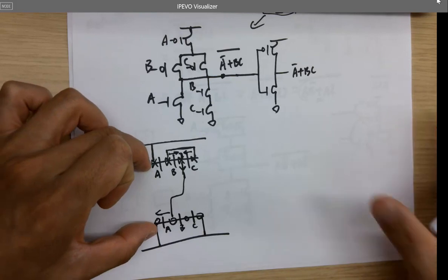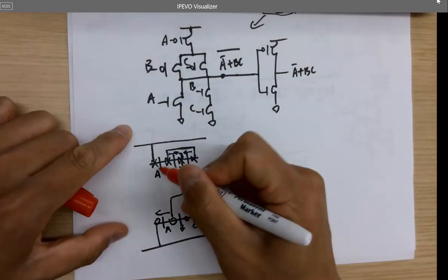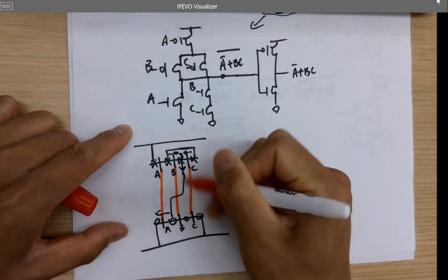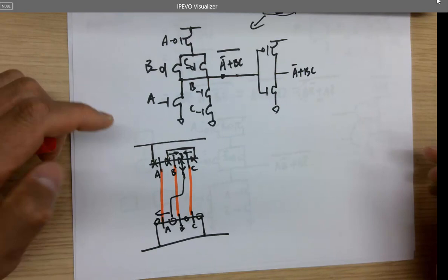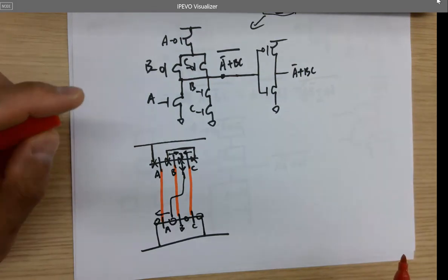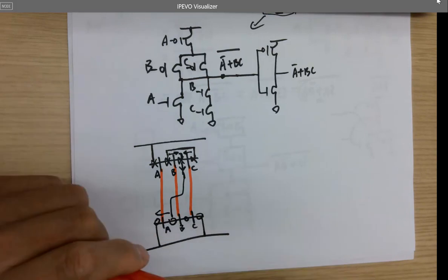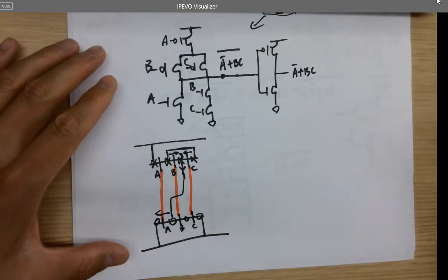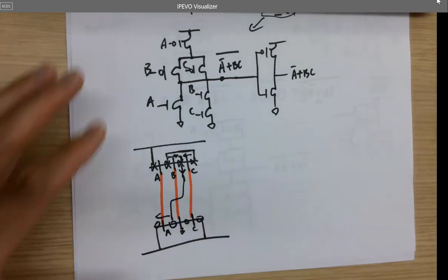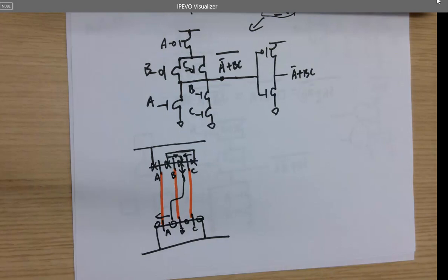Okay, so that's the layout for PMOS and NMOSes. And you know that the poly should be connected together. So directly draw a poly from top to bottom and short them together, so it's one signal line, the same signal line. Okay. But it's not done yet. We need to add an inverter to it, right?